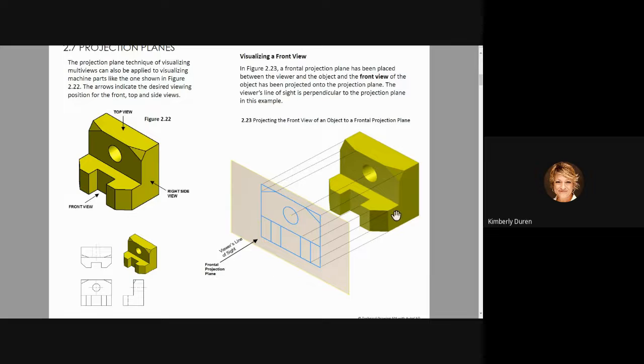We cannot measure angles in this front view. I can't tell you how long that line is or whatever. It's foreshortened. But in the top view, I can certainly put an angle there and there, or the length of that line, or put X and Y dimensions. So it takes as many views as necessary to describe the correct size and location of each feature.